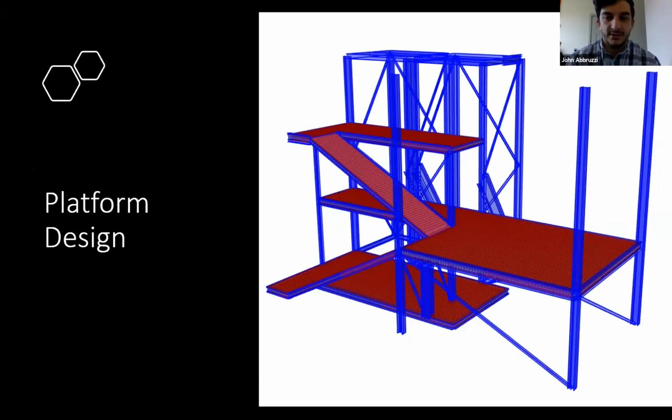To create the custom models in AutoCAD, the slabs and stairs shown by the red squares on your screen had to be drawn as 3D faces in their own layer of the drawing. The frames shown by the blue lines were then modeled as line elements in their own layer on the same drawing. The drawings were then able to be imported into SAP. SAP would read the 3D faces as a customizable mesh while reading the frames as beams, columns, and lateral bracing. Lateral bracing was used to prevent collapse of the structure once it experiences horizontal loads.